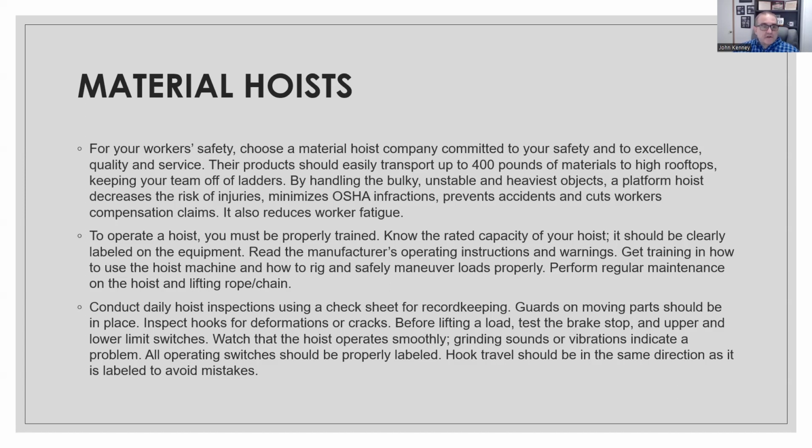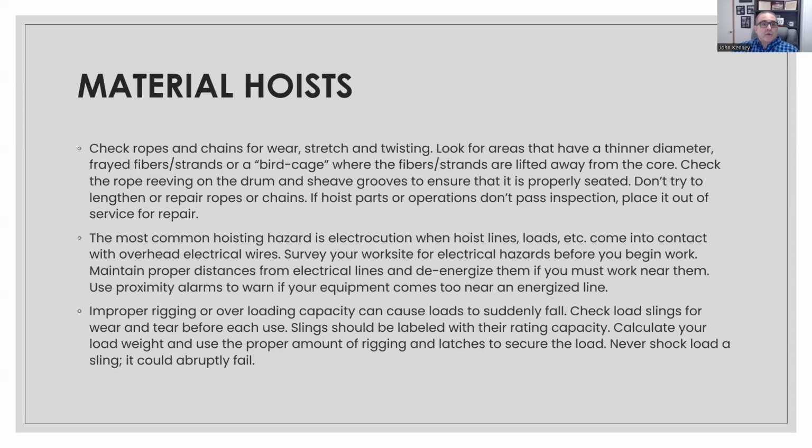Guards on moving parts should be in place. Inspect hooks for deformations or cracks before lifting a load. Test the brake stop and the upper and lower limit switches. So again, if you're hiring a contractor outside, like an equipment rental, or somebody supplying an operator of this equipment, make sure that they have this internal process in place to check everything on a daily basis before lifting actually occurs. You want to check the ropes and chains for wear, stretch, and twisting.